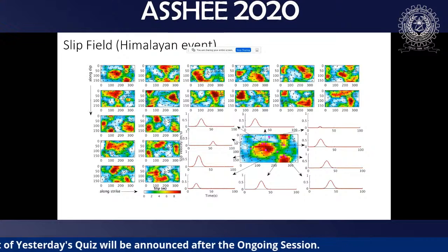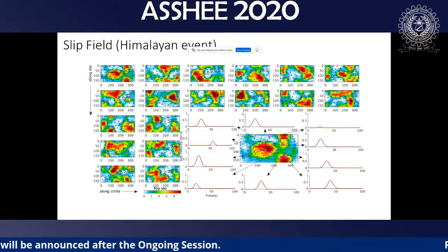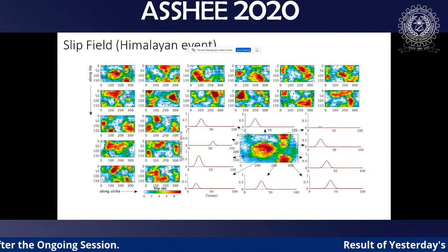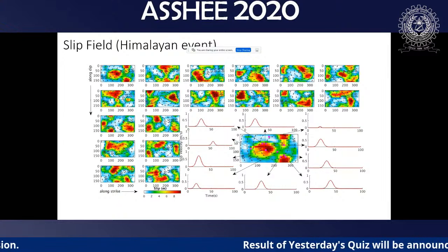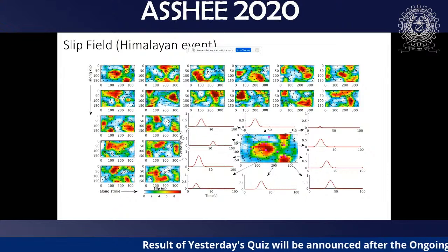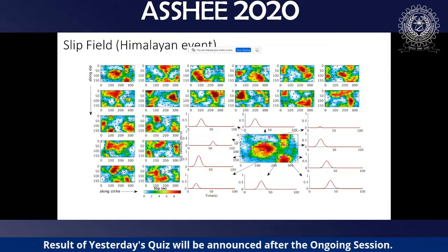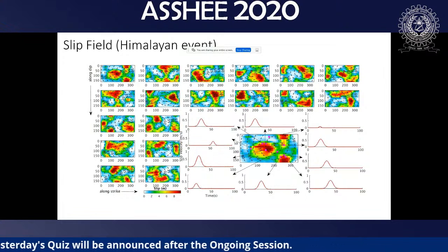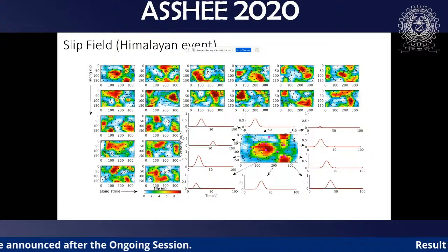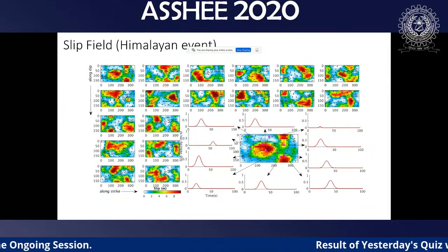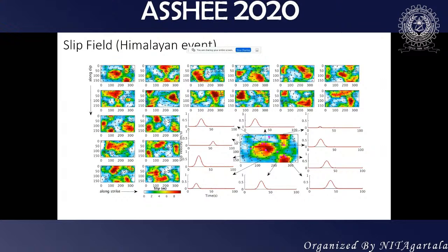So these are the slip models. We have our own slip model, the non-Gaussian slip model. We have developed a new model based on the past slips, and that paper is available in the Journal of Seismology. Using our non-Gaussian slip model, we simulated several synthetic slip fields. Here, for the correlation length, we have used the variogram technique. The correlation lengths have been taken based on the magnitude. Then the scaling relations, we have developed the equations for that. Then we model the slip value as a truncated exponential distribution. This is the slip I'm showing you; we have generated several slip values to understand the effect of slip on the ground motion.